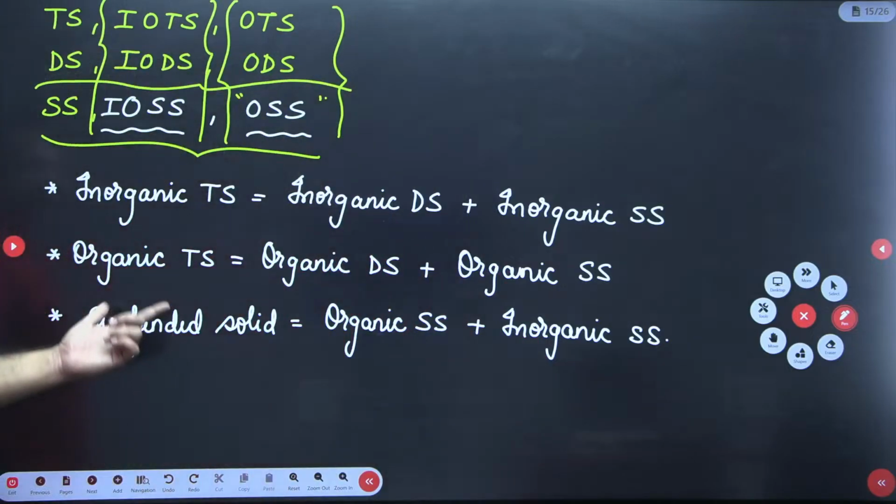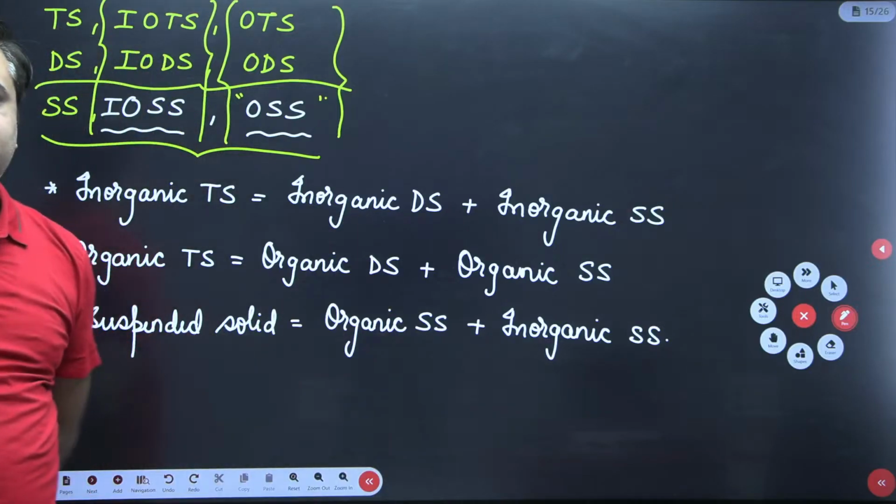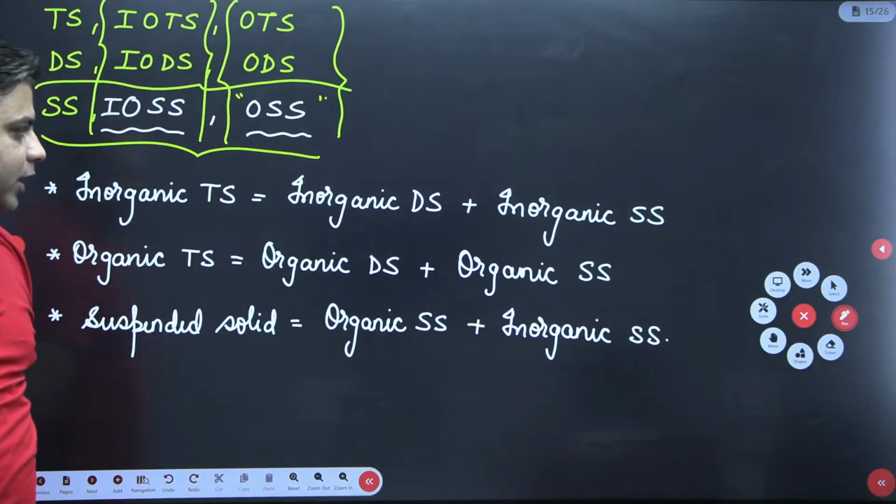So you know the concentration of suspended solids, you know the concentration of inorganic suspended solids, you can calculate the concentration of organic suspended solids, right?